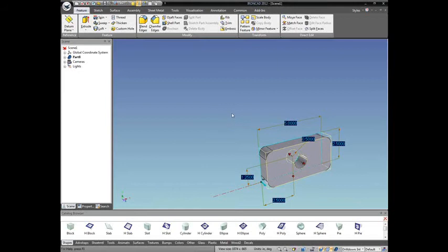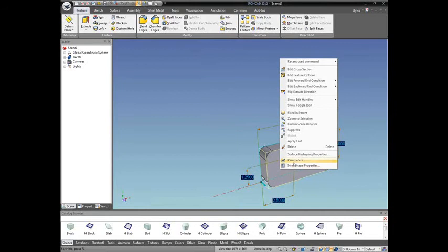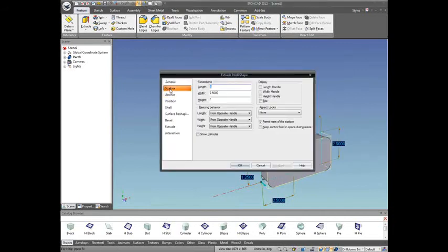And you have to go to the size box. Right. You have to go into the size box. Yeah. And that's where, let me kind of reiterate that. Go into IntelliShape Properties, and you go to Size Box, and click Show Formulas. And that will let you type in the parameter that you created in the parameter table, so that shape's height always knows to go back to the parameter table for its value, and it's looking for the parameter THK.